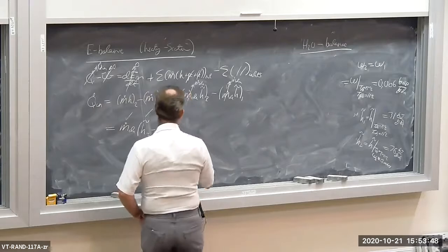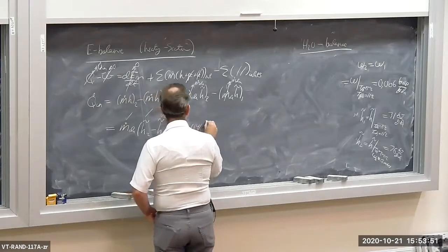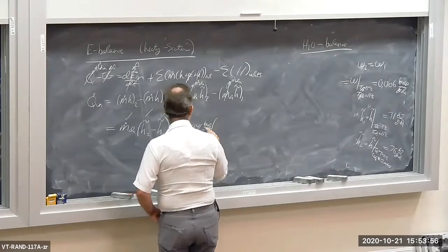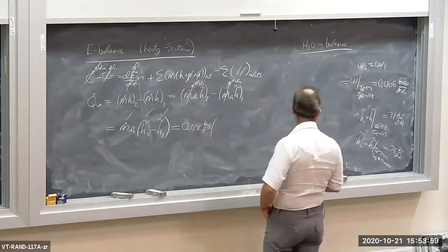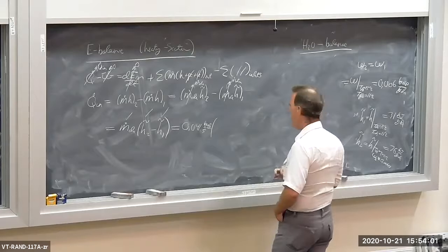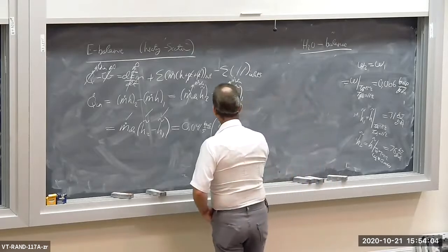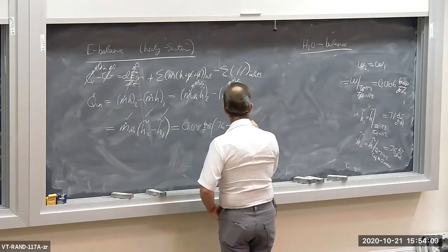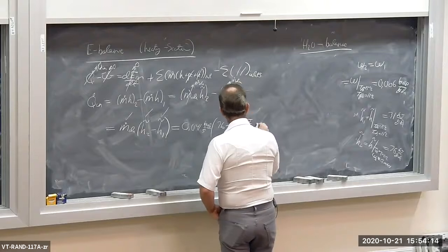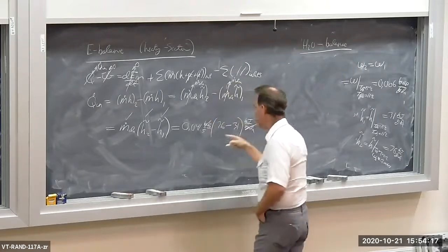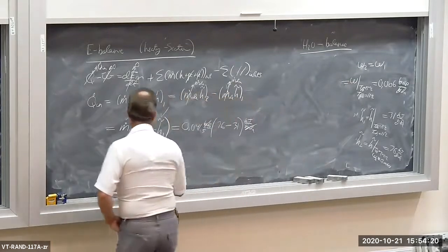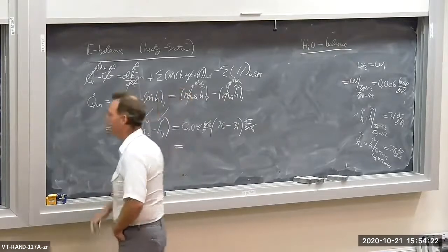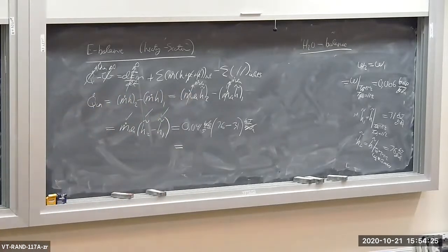All right, m dot dry air, what was it? 0.041 kilograms per second, and that's kilograms of dry air per second. Make sure you keep the unit dry air, not moist air. And then I have H2 tilde, which is 36. H1 tilde is 31, in kilojoules per kilogram of dry air. Notice the dry airs cancel out and I get kilojoules per second or kilowatts.